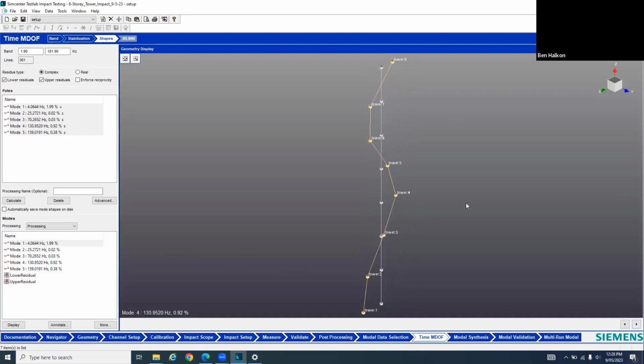Let's have a look at the fourth mode shape. Importantly, now you can see these crossings of the zero axis, and that's characteristic. Increasing spatial density for higher frequency shapes. 2, 3, 4 locations along the tower where I don't have any motion for each of those shapes.